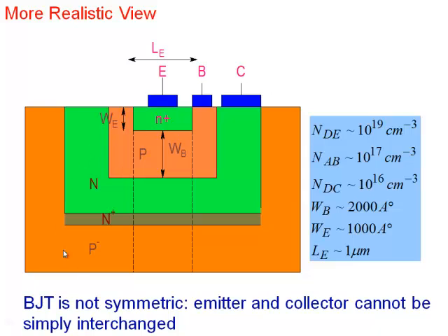And typically what would happen is, as I said, you start off with a p-type silicon wafer, and then you successively add impurities, n-type and p-type and n plus and all that, and then you make the transistor on the silicon wafer here. One after another, you add different kinds of impurities and in selective regions, and you make the transistor here. This N plus region that you see here has been made because the electrons start from emitter, go to the base and come to the collector. But eventually, where do they have to go? They have to go all the way here. And in order to minimize the resistance, an N plus layer has been created here.